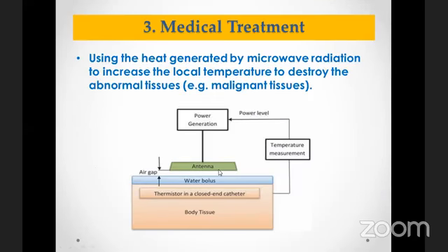An RF antenna is placed, and you know the principle of microwaves. The water gets resonated and it gets heated up. Temperature increases. This temperature is sensed by the system. It reduces the power. Antenna reduces its radiated power, and so on. These systems have been developed with 1300 watts power of RF for heat generation.